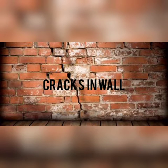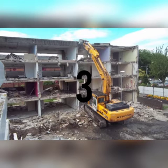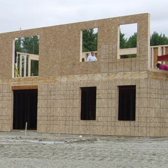Shoring can be used in these cases. Number 1. Cracks in wall due to unequal settlement of foundation. Number 2. Bulging of wall due to lateral pressure. Number 3. While pulling down the adjacent structure. Number 4. When openings are to be newly made or enlarged in a wall, etc.